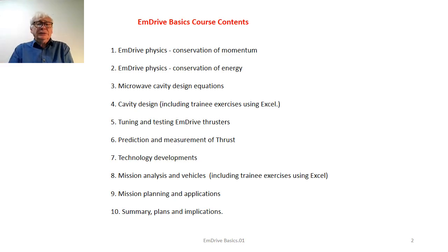Lecture 5 will cover the tuning and testing of EmDrive thrusters. The tuning is particularly important because if you don't get it right, you will simply dissipate all your input power in the input circuits of the thruster rather than dissipating it in the cavity, which is what you need to do to get thrust out of the device.